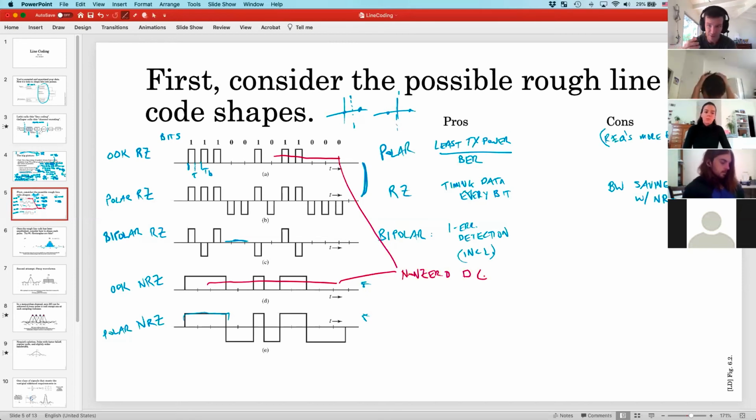because if you have multiple links in your communication system, often the way that one link is linked to another is via AC coupling. And if you have information in your DC signal trying to pass that through an AC coupled interface, you're SOL.